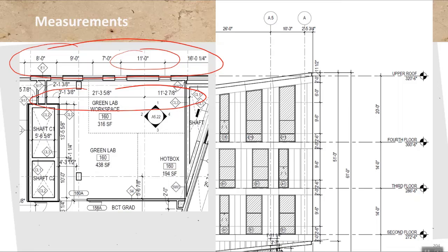So how do you dimension? This very much depends on convention, materials, etc. So for interior, you very often do surface type dimensions, interior surface to interior surface. Although interior partition walls are typically dimensioned at the center line, in this project they're not. They're actually dimensioned at the surface line. But this is very much a convention that you need to figure out project by project.